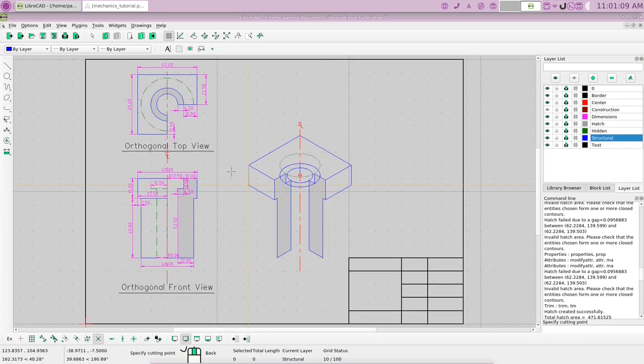Well, if we snap on an end point, we could snap right there and cut that there. Now let's choose it again and snap on end point there. Now let's right click to get rid of that. Let's highlight that piece that we took out, hit your delete key, and it's gone.